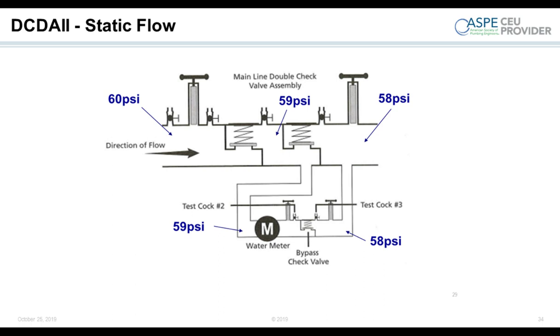So let's look at a more basic diagram. Here's everything broken down nice and easy. You have your main valve, two 1 psi checks, and you have your bypass, a meter and a single check. Many of you might be thinking, well, hey, those bypasses are cross-connections. Cross-connections should have backflow preventers. A single check is not a backflow preventer. This seems like it shouldn't have been approved.